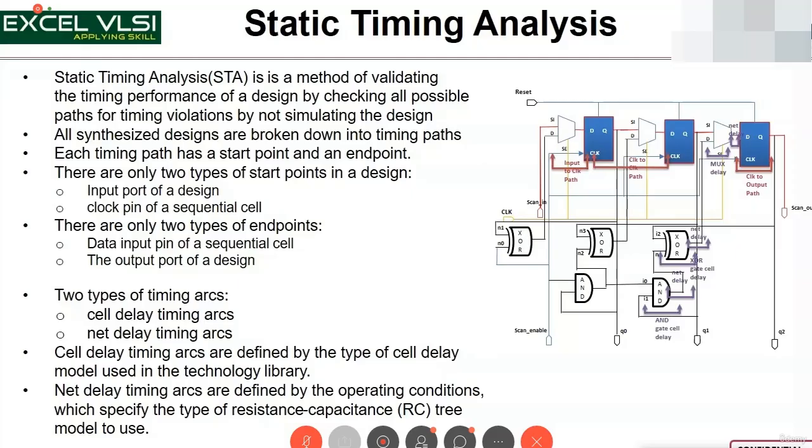At the high level we will be doing functional checks, but through gate level simulation you cannot do the timing analysis at this granular level, taking every cell timing arc. So we do the static timing analysis, one level, and dynamic gate level simulation also, to get more confidence. Hope, Manjula, I answered your question.